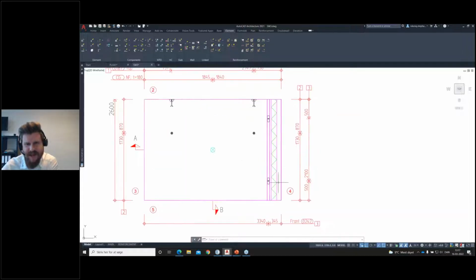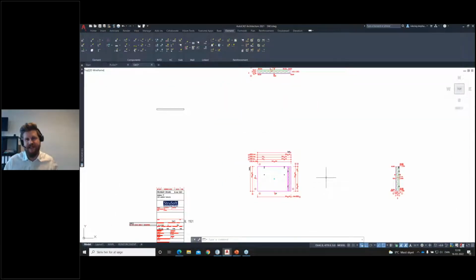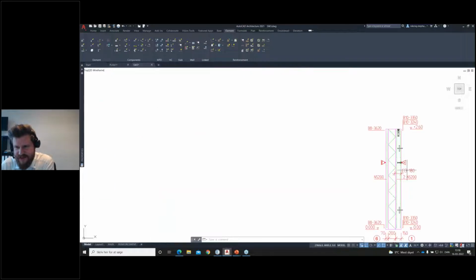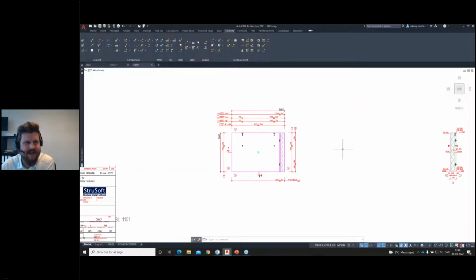So here it's very easy to see that we have some insulation. Nobody will misinterpret this. Some might have it shown as yellow instead of green as I have here, but it's just a matter of colors. That's basically it for that feature, and it just does it, so you don't really have to do anything, which is the case for most of the things we're going to show you today. Some of them you can set up, but basically all of them are automatic. That's the whole point, of course. But that takes us to the lifters. As you can see, we have these small lifters here, which are placed in the center of the back panel and not in the center of gravity of the panel. And this is completely on purpose.